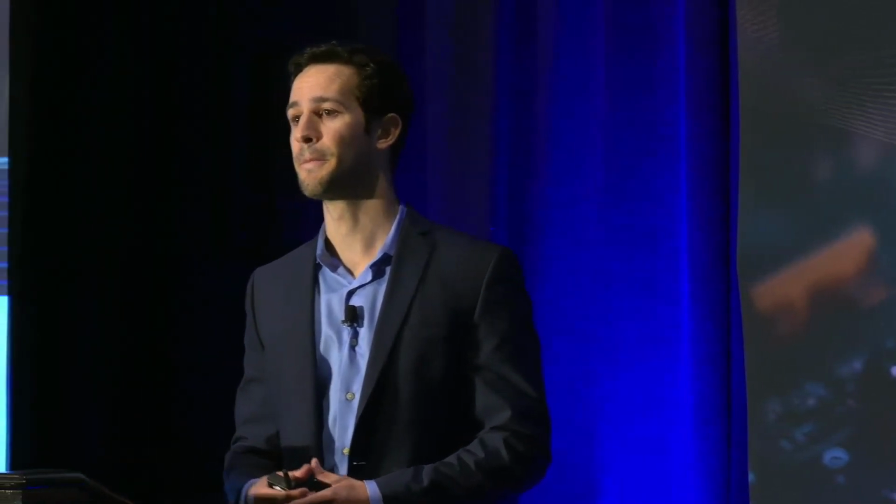Hi. You mentioned in-memory compute. Can you say a few words about how you do the in-memory compute? Most of the time people talk about that in conjunction with analog computing. Yeah, absolutely. I can contrast it with analog computing. In analog approaches, the most common approach is that you store your array on some sort of resistive memory or PCM. And you store it in a crossbar structure, and then you apply voltages and read currents, and you leverage quite literally Kirchhoff's laws to do multiply and accumulate.